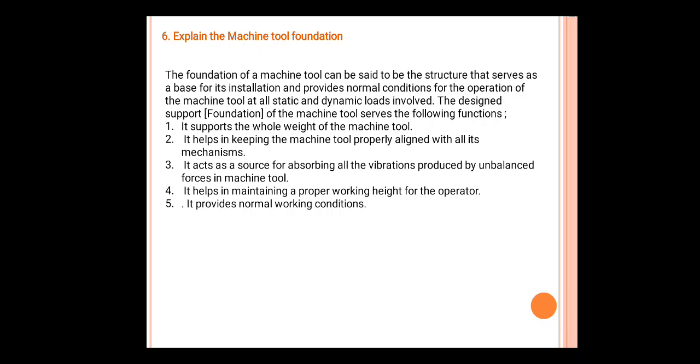The foundation of a machine tool can be said to be the structure that serves as a base for its installation and provides normal conditions for the operation of the machine tool under all static and dynamic loads involved. The designed support of the machine tool serves the following functions. First, it supports the whole weight of the machine tool. Second, it helps in keeping the machine tool properly aligned with all its mechanisms.